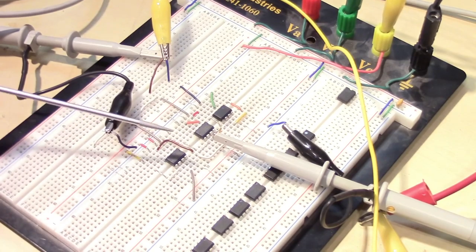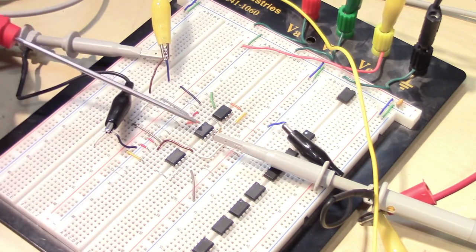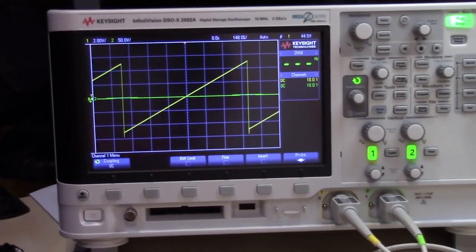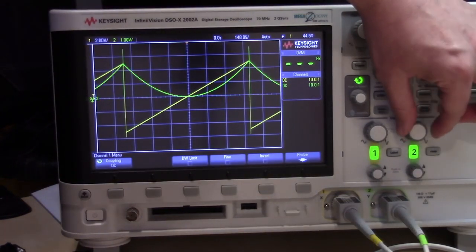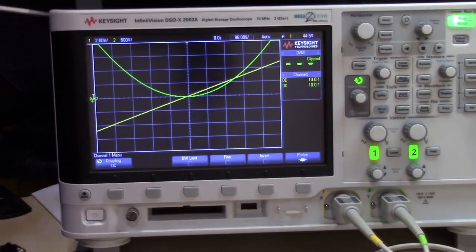So all I have here are the 2 analog multipliers with a little op-amp buffer up front, and I'm feeding them with a sawtooth input. And right now I'm taking a look at the output of the first analog multiplier. So that's going to be the input voltage squared. If we move over to the oscilloscope here, you can see there's my sawtooth input. And if I zoom in here on my channel 2, you can see that is the typical curve you get for a squared function. So you can clearly see that the input voltage here in yellow is being properly squared and output from that first analog multiplier.